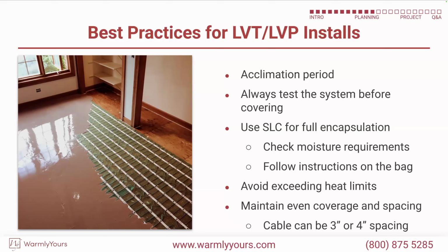Use SLC to fully encapsulate the system. SLC is the abbreviation for self-leveling cement. You'll see us throw that one around a lot. We love that one. Use SLC to fully encapsulate. When using SLC, you're going to want to check the bag instructions and follow exactly what the bag says. You're also going to want to maybe have a moisture meter to check the moisture for the requirements also stated on the bag of cement you use.